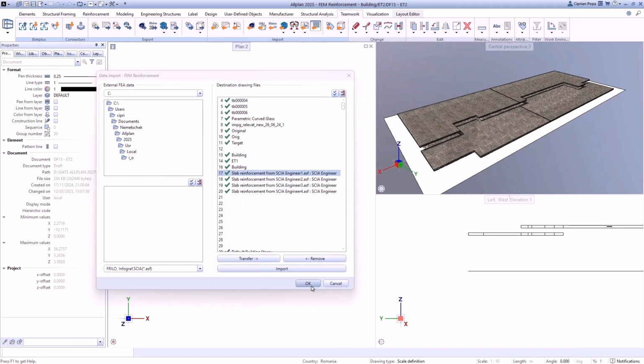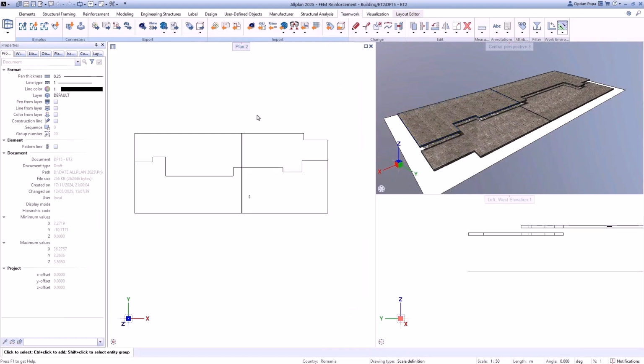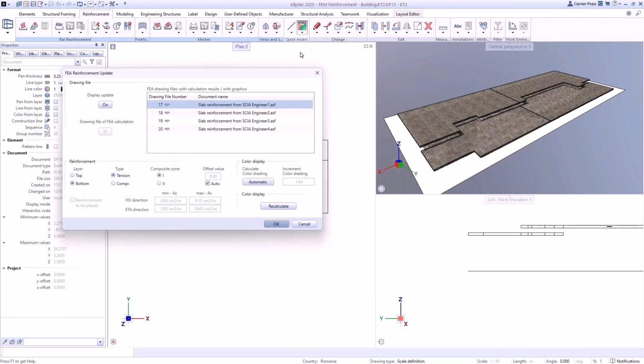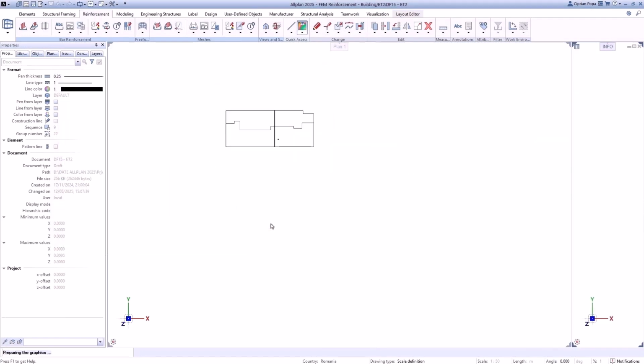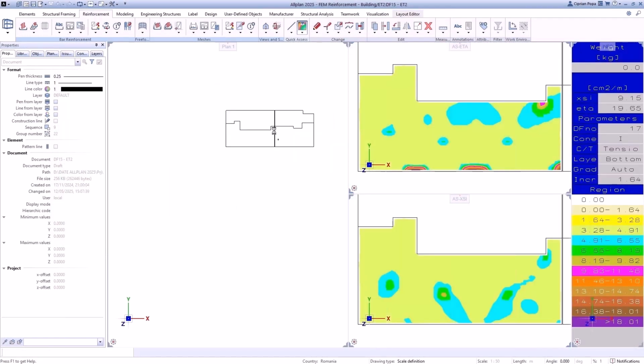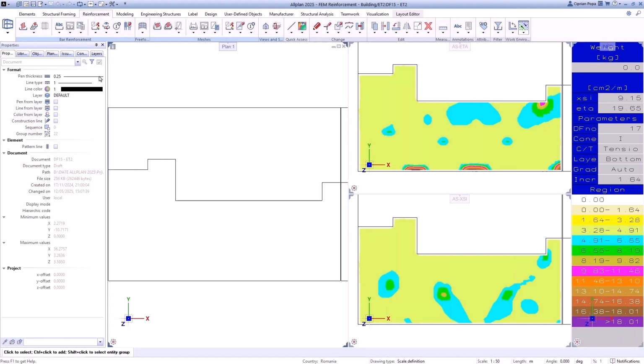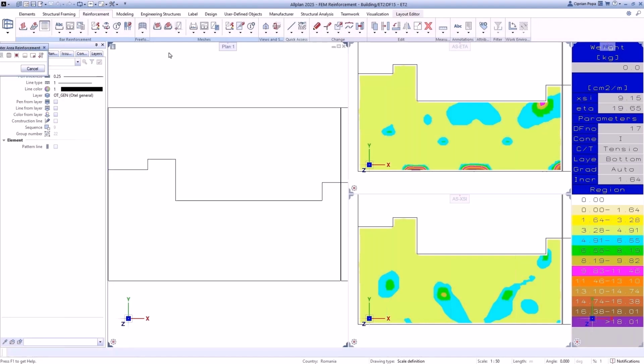The IFC should be at the same coordinate, that's one condition. And then we can start reinforcing realistically in Allplan, and this can be done by a draftsman. So an engineer maybe calculated the required reinforcement, just shares the ASF file, and the draftsman, or the engineer who's doing the detailing, just uses natural Allplan functions.